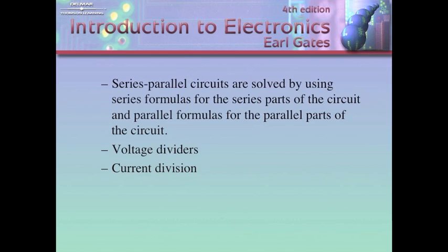No. That was a very good question. That was the total load current. That's the total, that's this current and this current. This is the bleeder current. So if we look at 20.5 plus 2.05, this is the load current plus the bleeder current. That starts the division process.